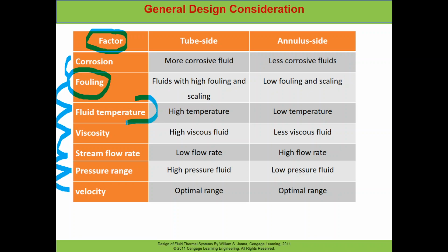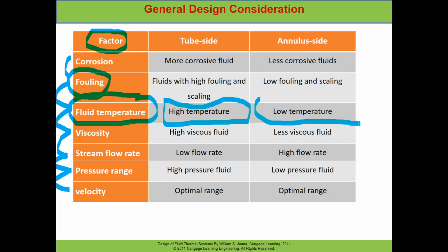The third criterion is the fluid temperature. The higher temperature fluid should be put inside the tube, and that is for safety reasons, and also to minimize the losses. Because if the temperature is low for the outer pipe, then the losses will be lower.